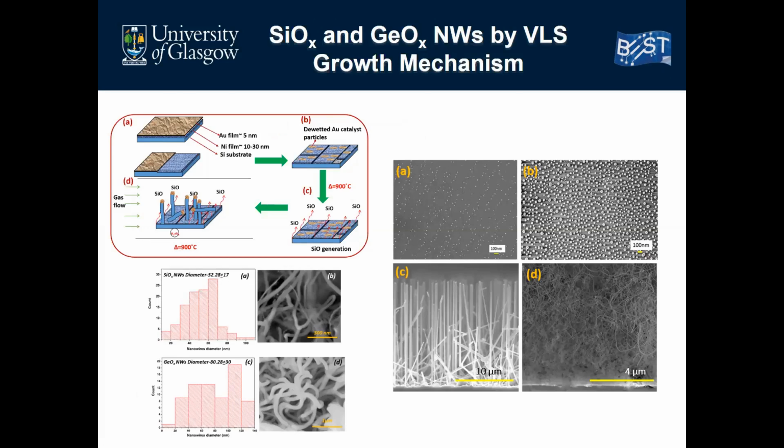This slide gives SEM images of amorphous and single crystalline nanowires for comparison, grown using the VLS mechanism. For the amorphous growth, there are only two amorphous nanowires grown to date: silicon dioxide and another oxide. Those are grown using the VLS mechanism with solid sources like thin films and silicon vapor, where the silicon wafer is coated with a thin film of gold as well as nickel, and nickel enhances the vaporization of silicon, so that it gets absorbed over the gold catalyst particle.